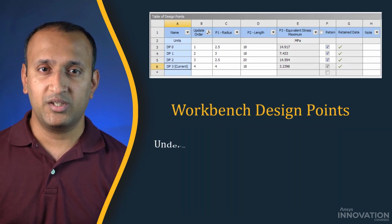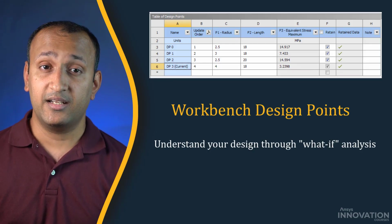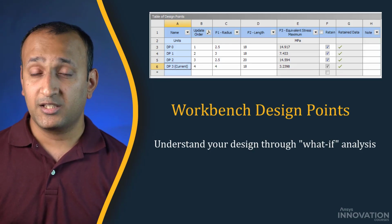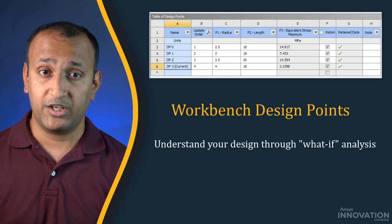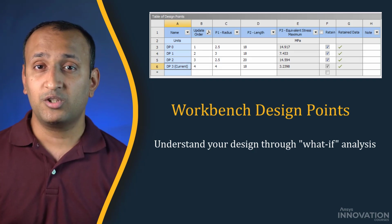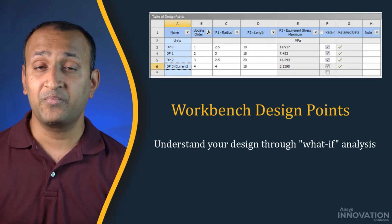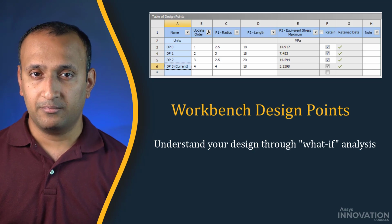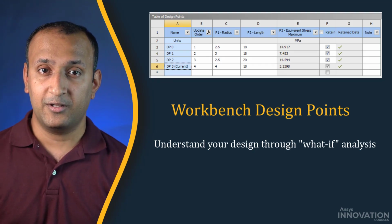What-if analysis using the table of design points is a first step in our effort to understand our design. It's worth noting that automated optimization tools such as design exploration or OptiSlang are also available, but are outside of scope of this lesson. Now, let's see how to set up, solve, and post-process a parametric model in our walkthrough example in Ansys Mechanical.